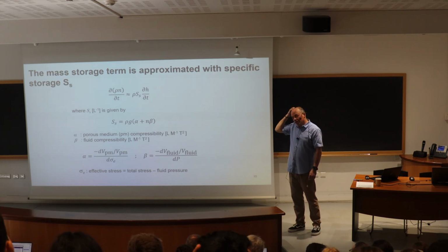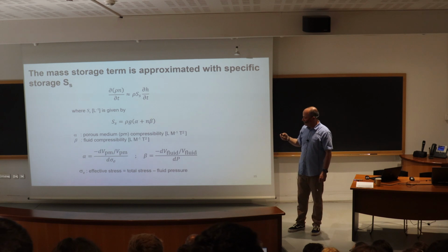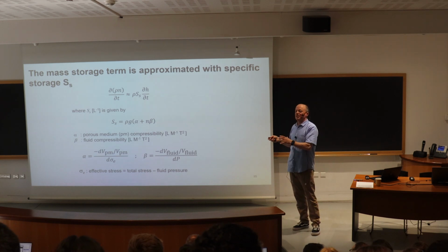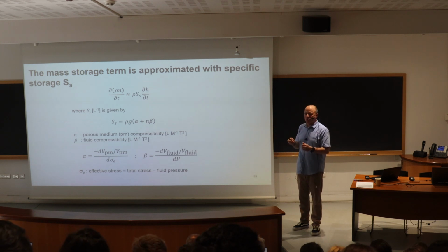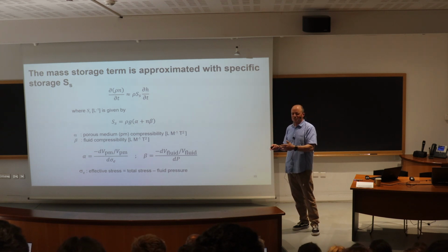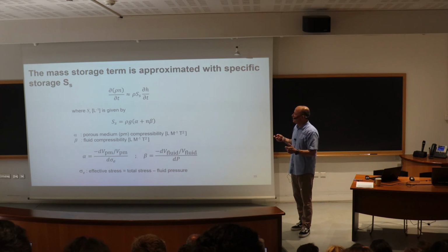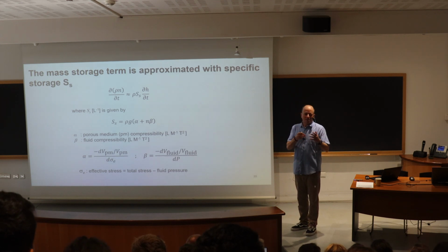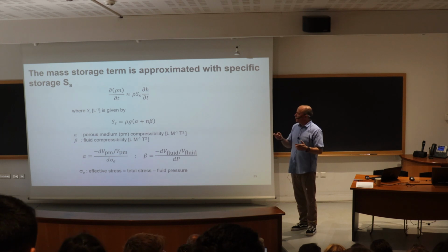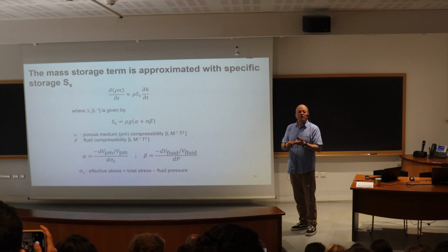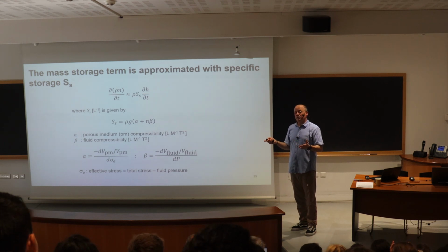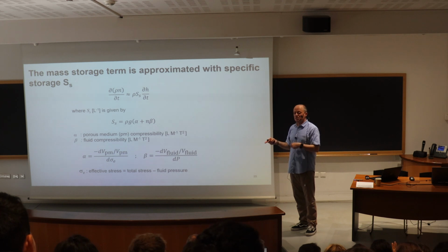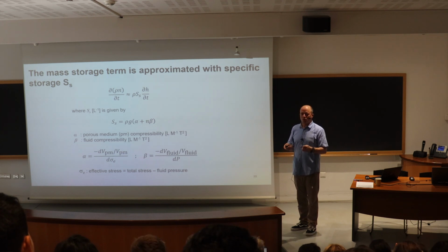If you are more into petroleum engineering, I remember talking to someone who was in that area, and I was showing that this is what we do in hydrogeology. He was quite shocked. Why do you do that? Well, it's because we have specific storage. Oh, what is this? In some fields, they will basically have relationships for density as a function of pressure, porosity as a function of pressure, and they will not make this simplification. We could still do it in hydrogeology because these relationships exist, but we like to work with specific storage.